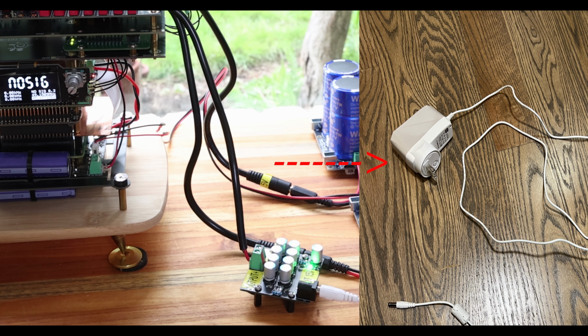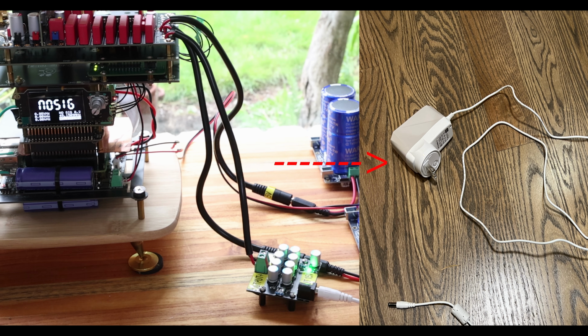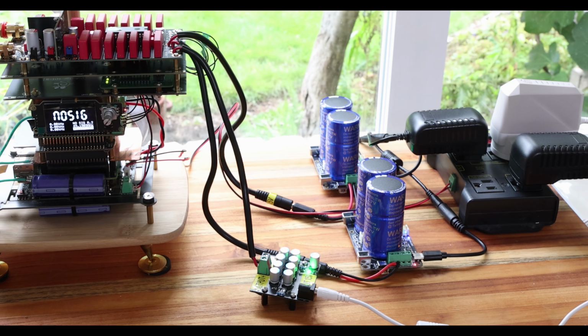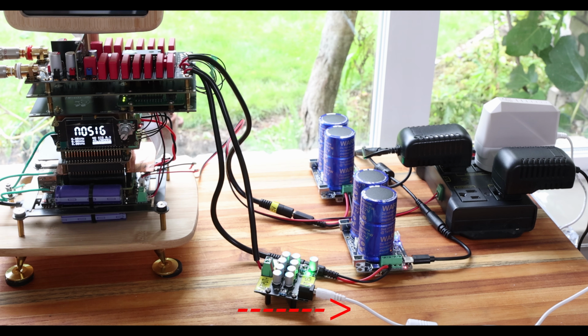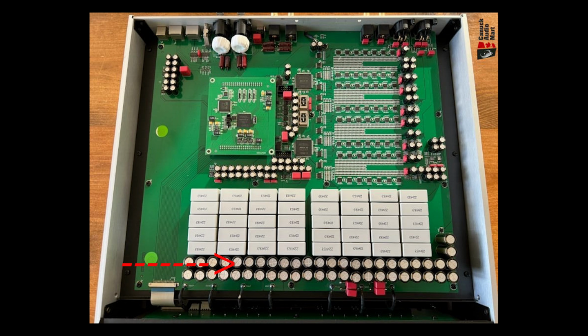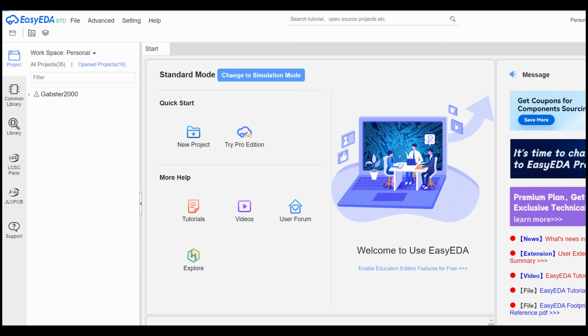If you take this i5 power supply, it has like a 5-foot long power cord. So by the time it gets to the DAC in this case, it's just going to be noisy. So if we put some capacitors close to the DAC, it's going to reduce the noise on that line. For example, the Denafrips Terminator uses such a technique. You can see here a whole bunch of capacitors. Sometimes when they're this close, they're also called decoupling capacitors. So let's build this power CRC filter.